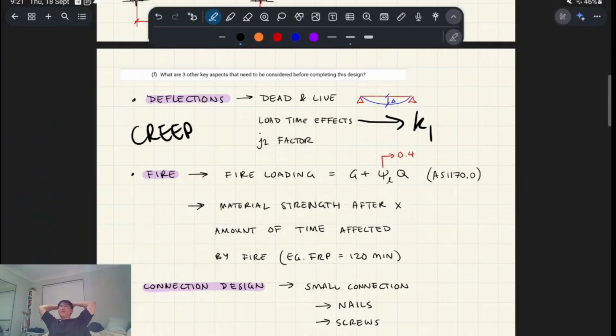Basically, if I had a timber board between my bed and this table, and I put a big rock on it, say it doesn't fail, right? But if I left it there for 50 years, there's a chance it fails, because timber will lose something like 45% of its strength over a very long period of time, 50 years. And this is due to creeping, right?